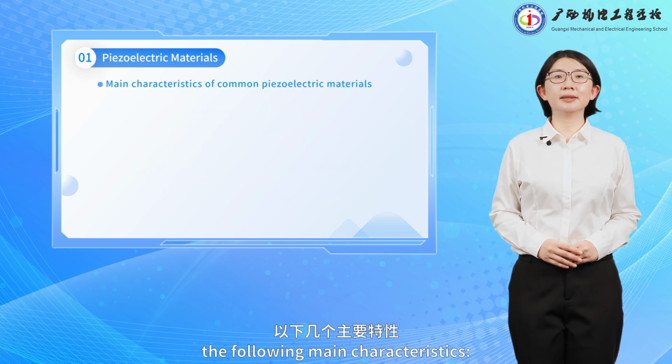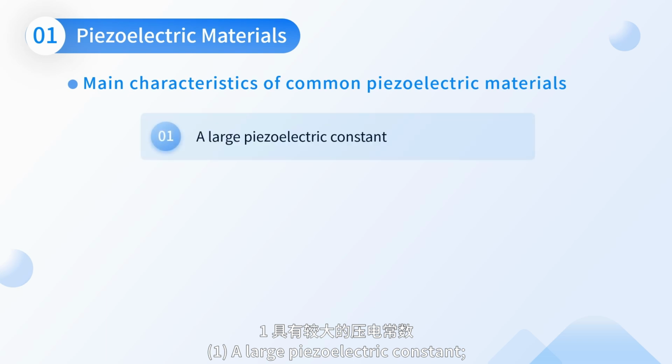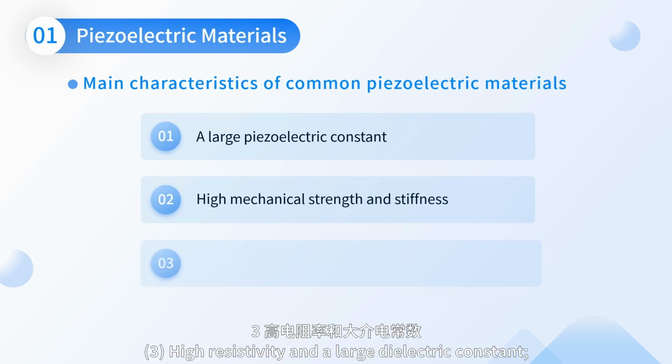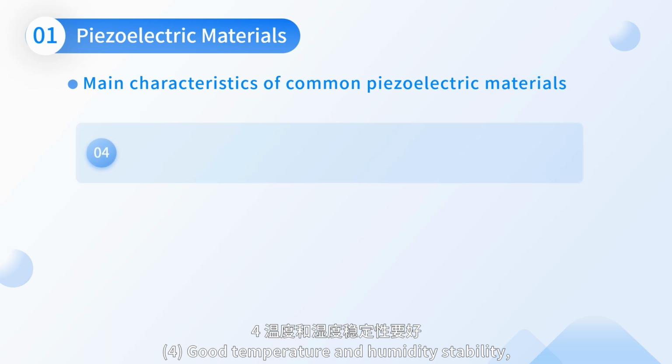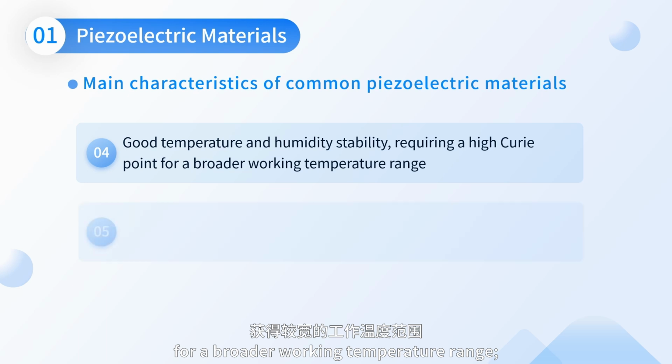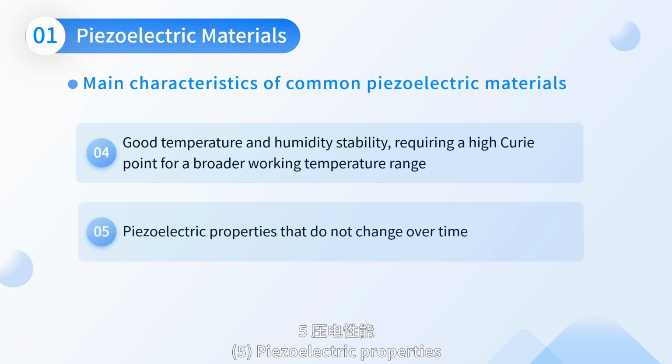Typically, they should possess the following main characteristics: 1. A large piezoelectric constant, 2. High mechanical strength and stiffness, 3. High resistivity and a large dielectric constant, 4. Good temperature and humidity stability, requiring a high Curie point for a broader working temperature range, 5. Piezoelectric properties that do not change over time.